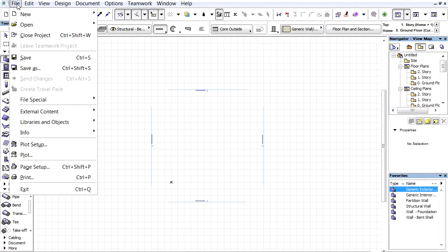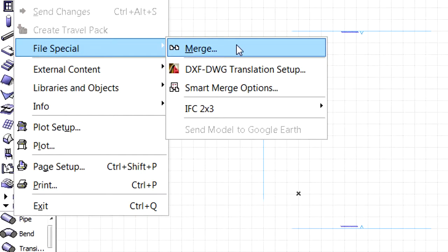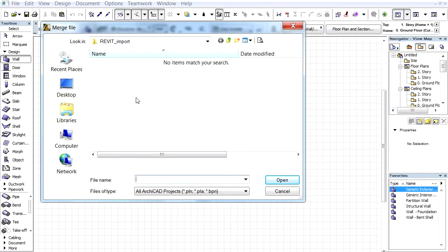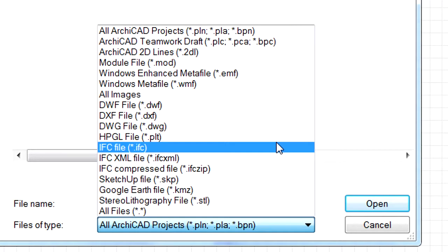Mechanical engineers and consultants who are using the 3D MEP application can send their work to the architects. The standard MEP parts will be converted into their equivalent ArchiCAD MEP library parts. ArchiCAD provides out-of-the-box translators which are optimized to import and export MEP data to external applications like Revit or DDS CAD. This open IFC system enables the members of the extended design team to use their own design applications for modeling. Using the IFC format as a common language, all parties can communicate and share the design while staying in the design environment which meets the local standards.